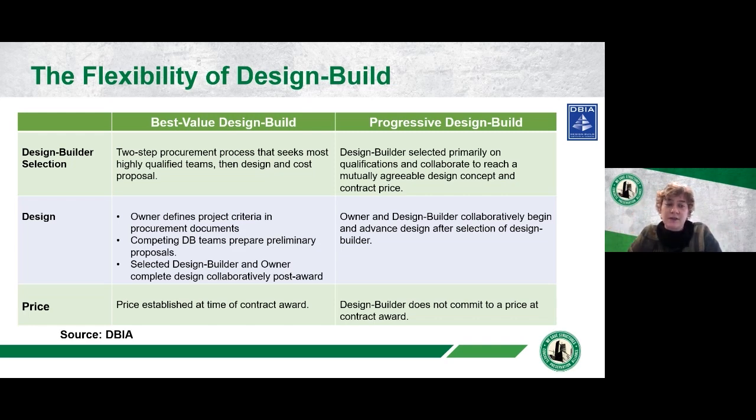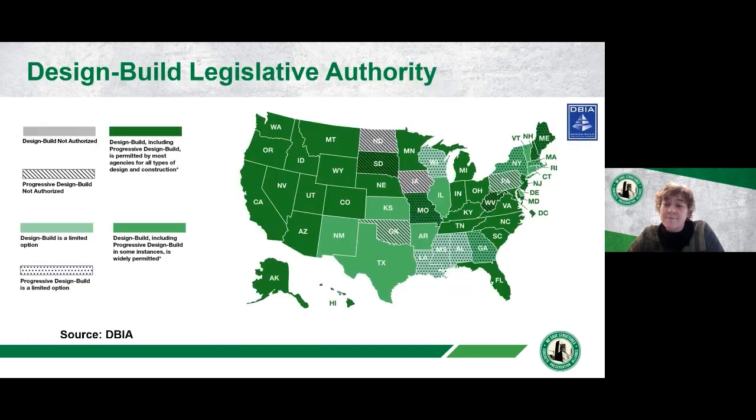holistically, the level of detail that needs to go into a best value design build is enough that all parties can have consensus that they understand the risks and they understand the full scope in a way that has meaningfully allocated what's occurring on the scope, and then how anything that's specifically highly risk related scopes has been addressed, whether it's owned by the owner or owned by the design builder. We've seen some best value design builds that will often require designing up to about 30% level. Other ones will be a little bit less, but that all just depends on the project details and complexity.